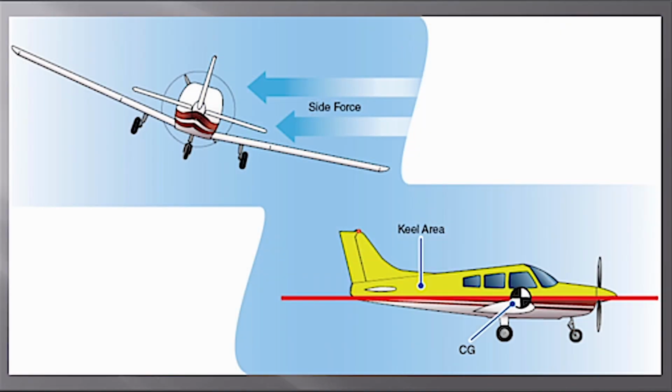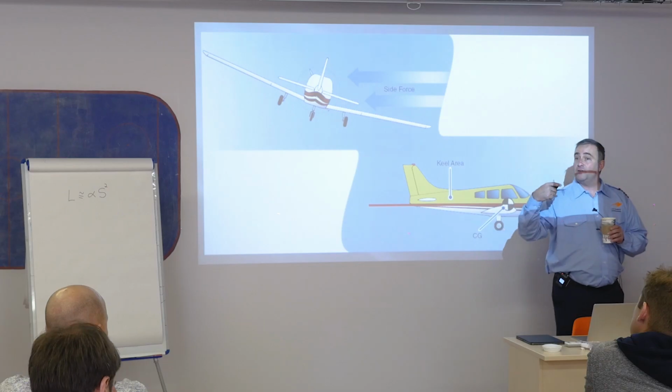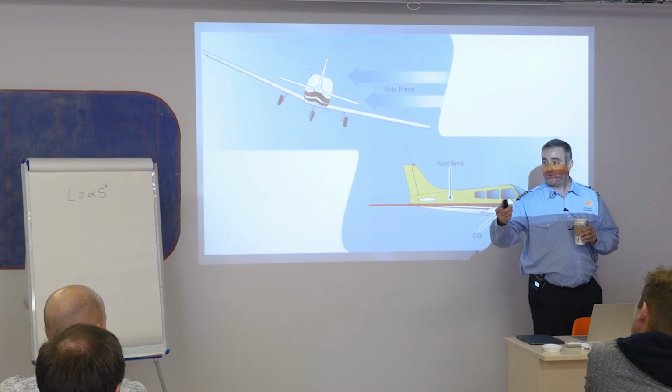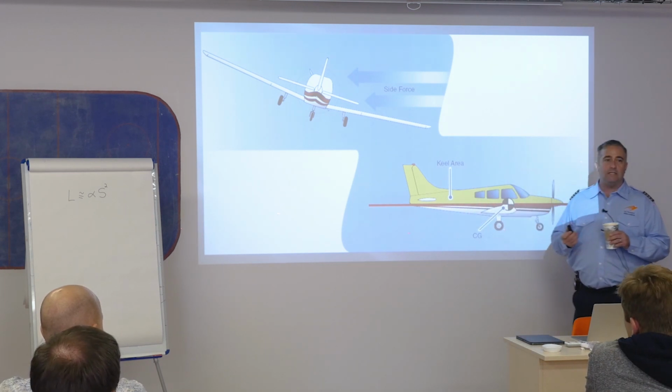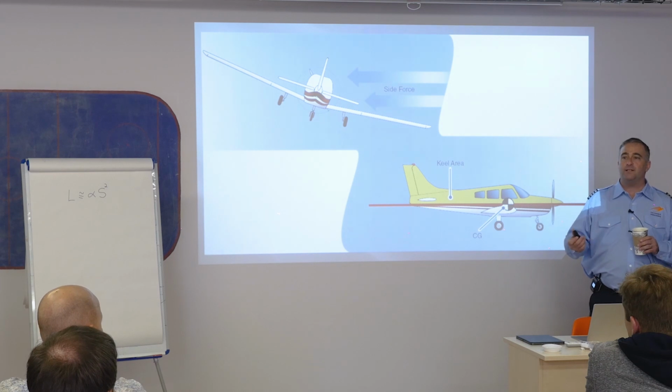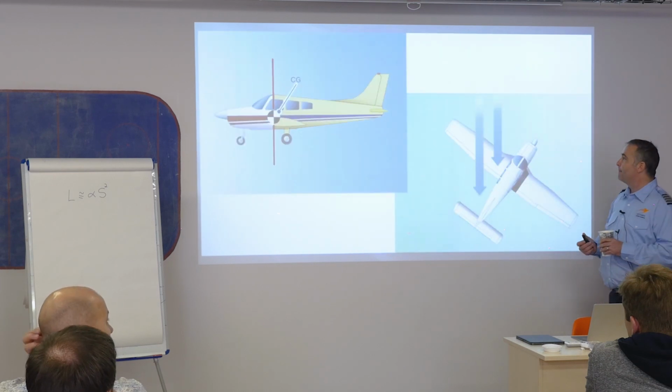Okay? All right, keel effect. The airplane does have some rigidity in space because as I'm moving forward, if the fuselage is exposed to the relative wind, that'll cause a force. And every force has an equal and opposite reaction, so that will also cause the airplane to straighten up. Again, all ideas that airplanes are inherently stable and easy to fly.